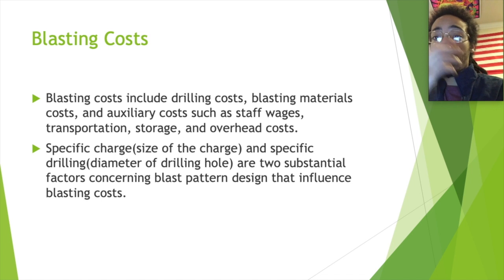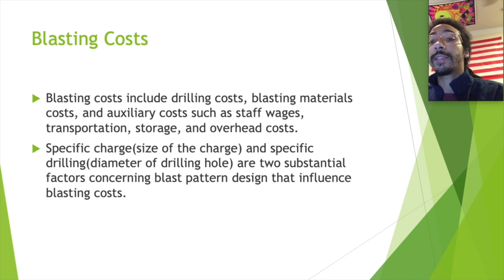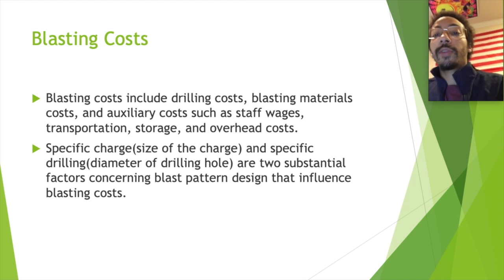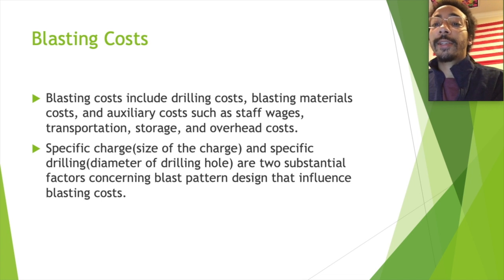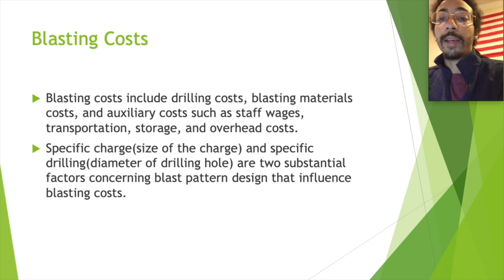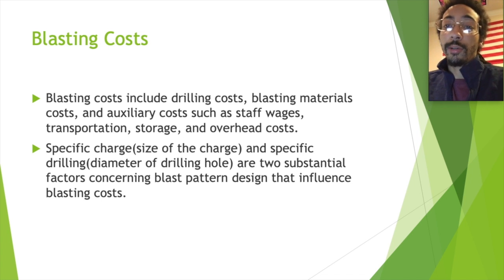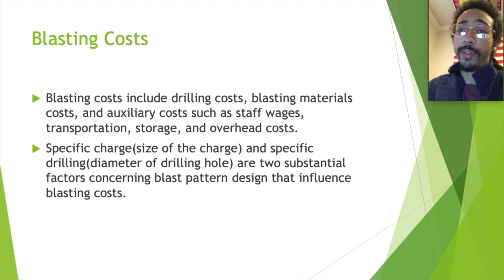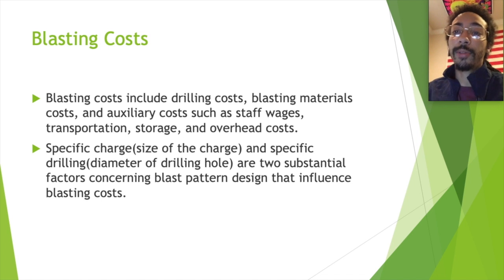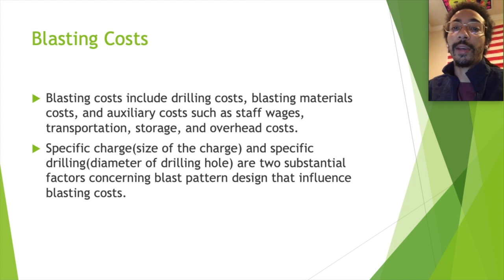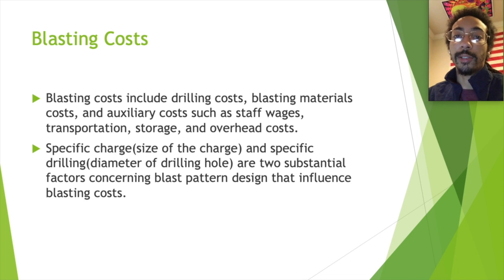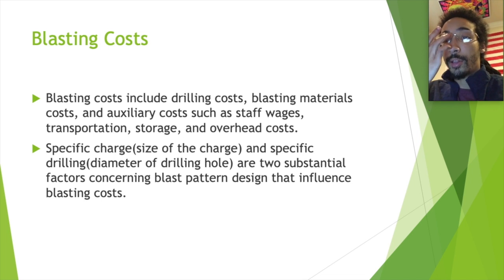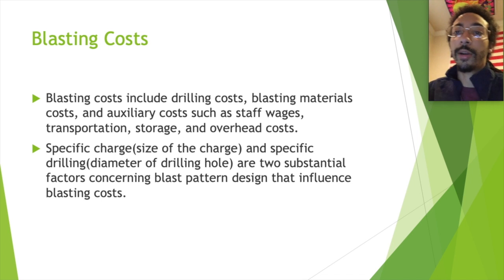A specific charge or size of the charge and specific drilling diameter of the hole are two substantial factors concerning blasting patterns when you're designing them that influence the blasting cost. So the diameter of the hole, how big of the hole you're sitting the explosive in, as well as the size of the charge itself, are two things that really go big into the cost, because the bigger, the more expensive, obviously, the more gunpowder you need, or the more dynamite, or whatever you're using.